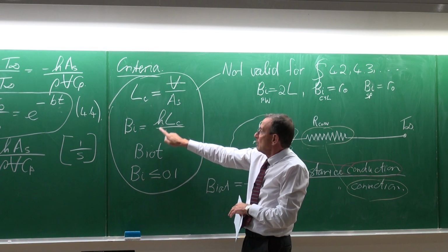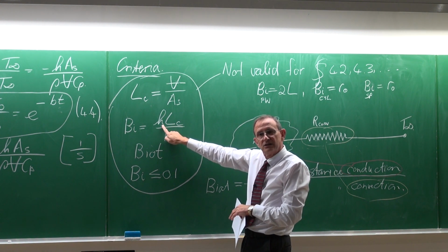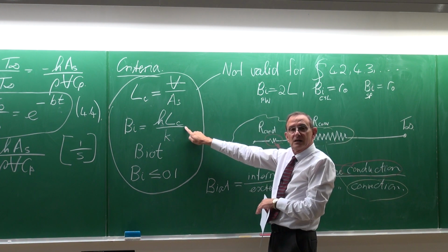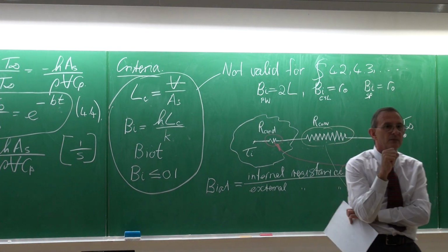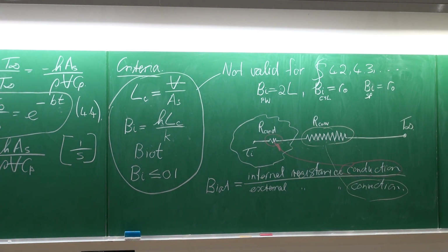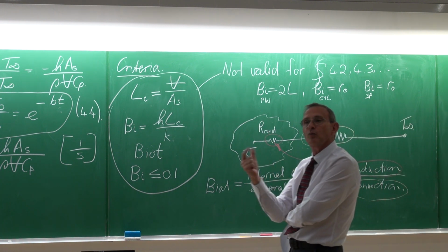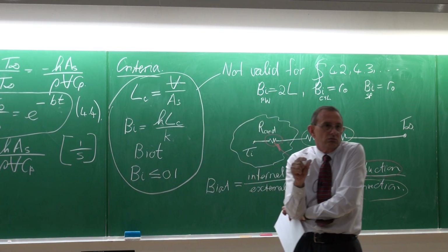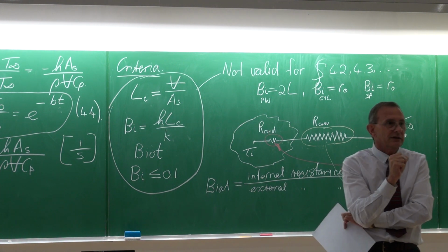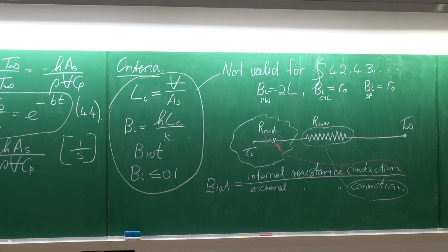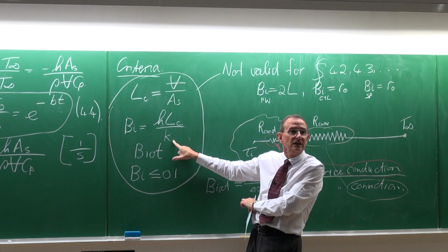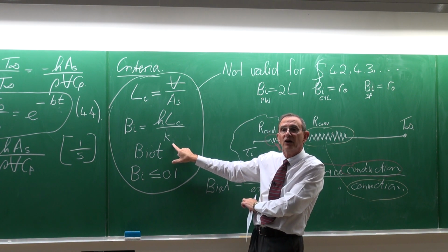So small Biot numbers are being caused by environments where the heat transfer coefficient is small. So normally natural convection. Then secondly, if the geometry is very small. Now, what geometries can you think of which are small? Well, small geometries would typically be a ball bearing, a small ball bearing. A small ball bearing will be small in diameter, so any object that is very small. And then the thing that really also helps is the thermal conductivity. If the thermal conductivity can be as high as possible.